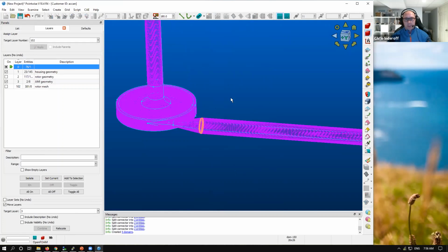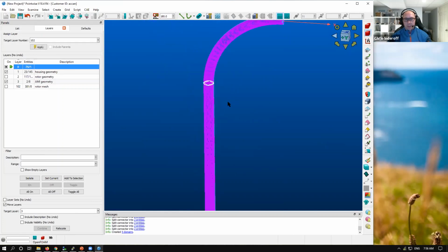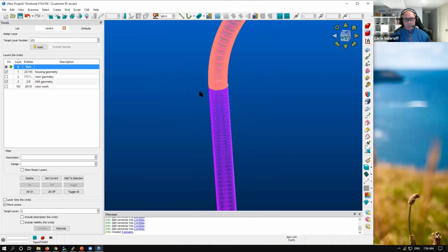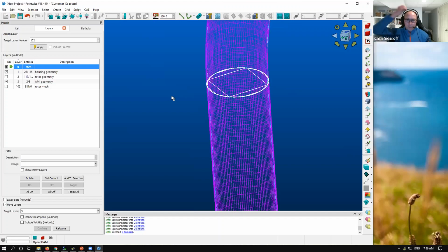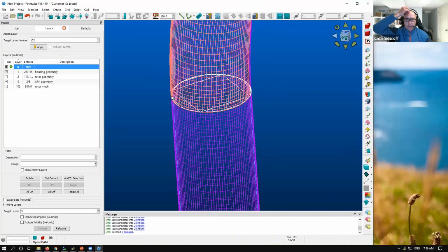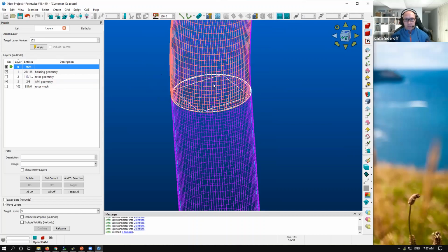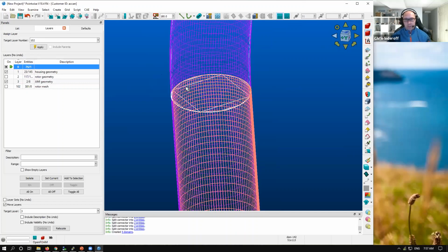So there's some funny business here at these other regions. The reason Pointwise messed up the mesh a little bit is that when you make domains or surface meshes in Pointwise, it will automatically try to constrain the interior points of the domain. In this situation, the connectors resided on the geometry, but there's actually no geometry in the middle where the circle is.